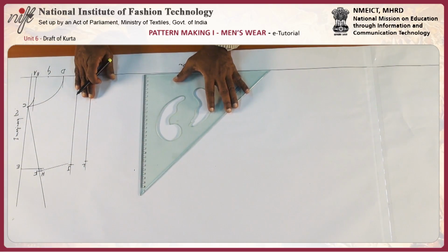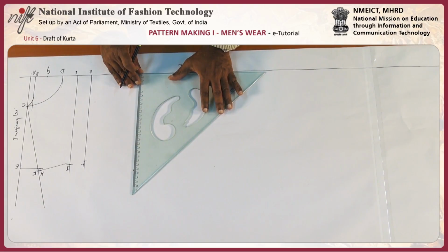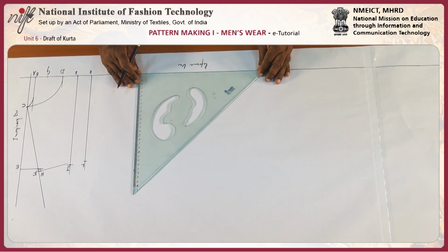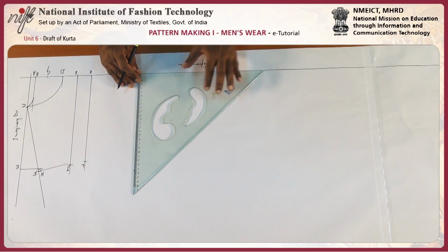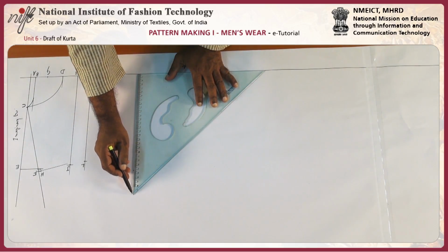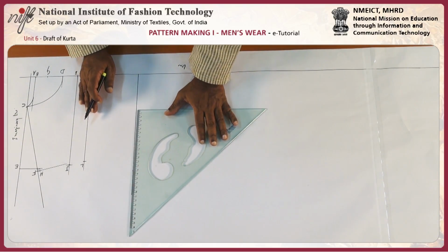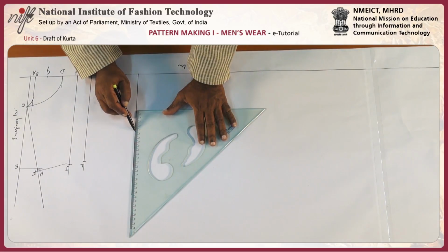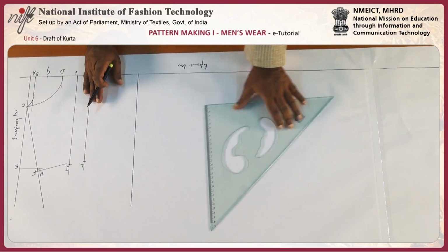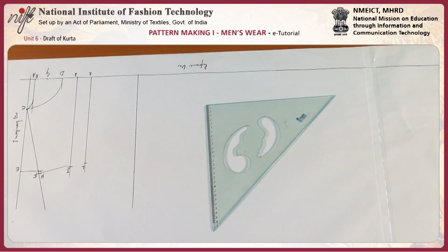For that point you need to draw a perpendicular line to the reference line, as I am showing on the diagram. This can also be extended for a certain length. The intersection on the reference line will be point N.